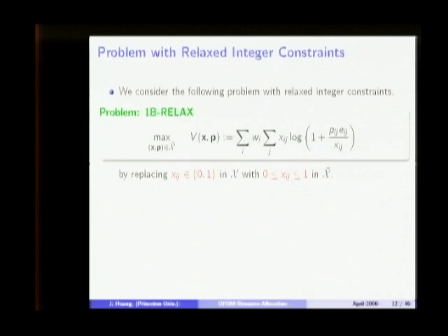Essentially, it says that if this is the power allocated to it, and this is the time fraction, for example, 0.5, so half of the time you are using this tone. Then at the active part, you are transmitting at twice the SNR, right? And then this is the rate you can achieve, the instantaneous rate, times the fraction you get. So this is indeed if you allow time fraction. The time fraction of power you are using is xij pij, right? pij is the allocated power, the total power allocated to you for this time slot. Then if you're only using half of the time, you can use twice the peak power during the active time.